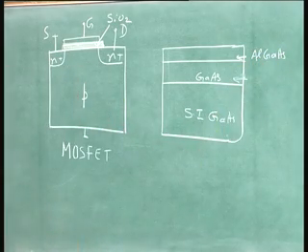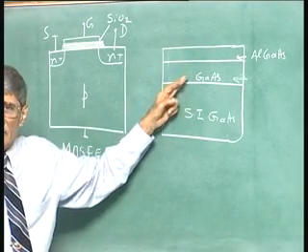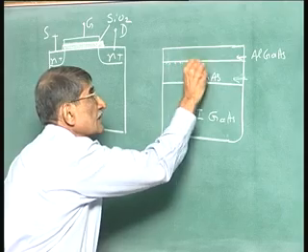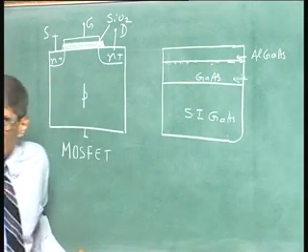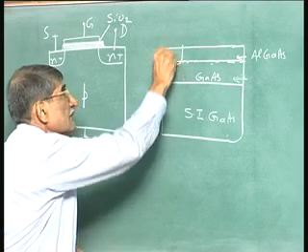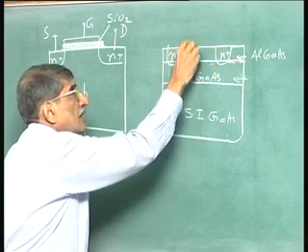So, what you have now is a doped layer and an undoped layer, which I have already put there. In fact, this will give rise to the two-dimensional electron gas. That diagram we have already been discussing. So, you have this n plus here, you have this n plus here, and you have a gate here.